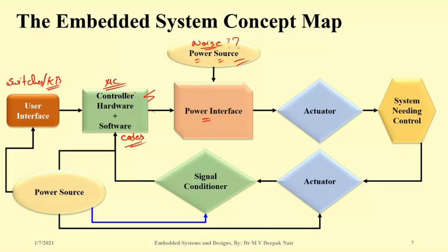Power interface means, because remember microcontrollers are generally low power devices. So that means you cannot drive a motor or a tube light or a fan or any high power electrical equipment using a microcontroller. So definitely, to increase the amplitude or the power of the signal coming from the microcontroller, we always have to depend on some power interface that will increase the power of the system.